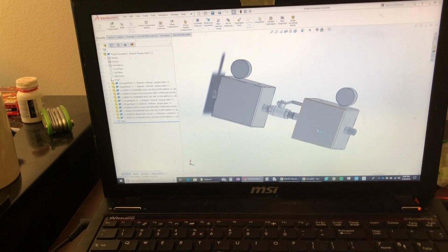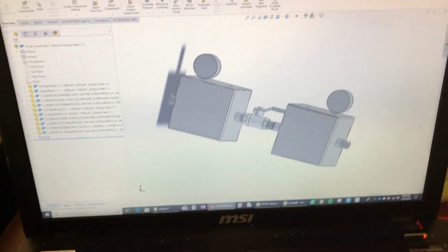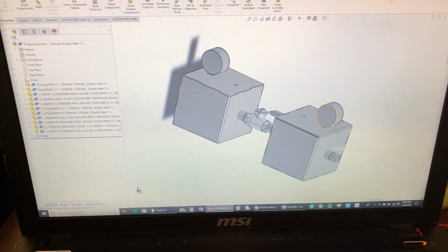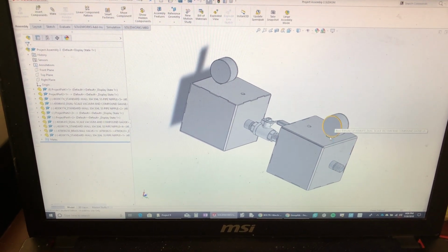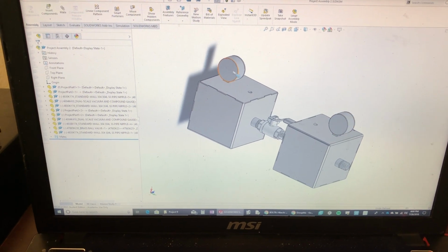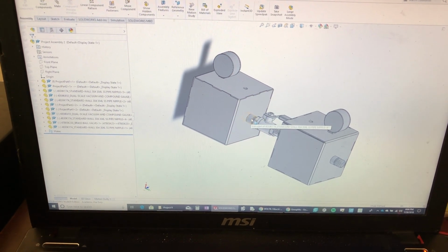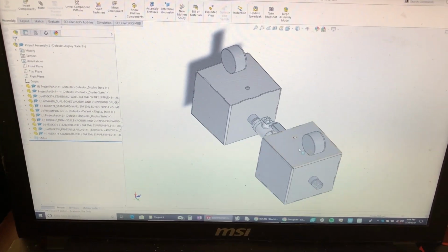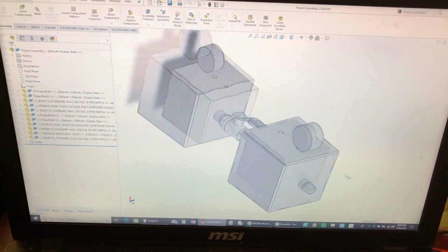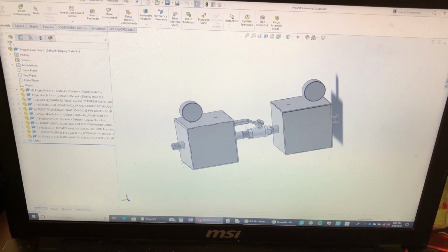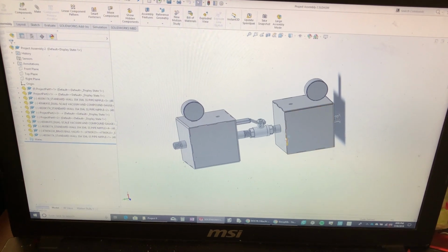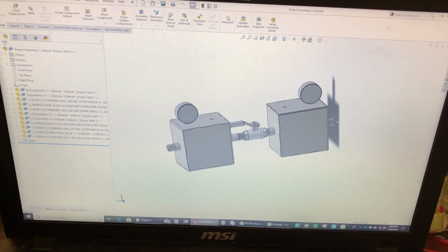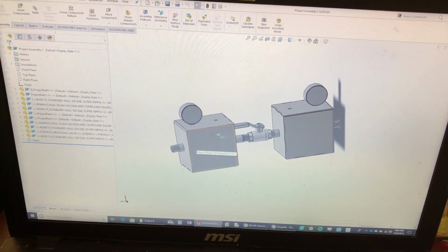Alright, so we cadded this up in SolidWorks, made an assembly out of the stainless steel boxes using SolidWorks sheet metal, found some parts from McMaster and downloaded their CAD models to match up for the temperature gauges, the 1/2-inch NPT nipples, the valve, and then we have our through holes here for the temperature probes. They're identical parts, so when they're made, they're going to be made the same exact volume. And then we'll have these exit holes and entrance holes for creating a vacuum and adding the helium inside of it as well.